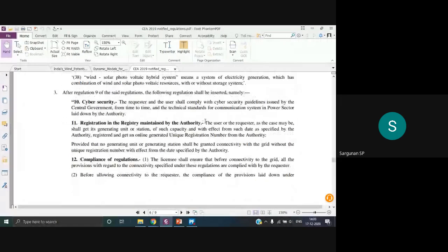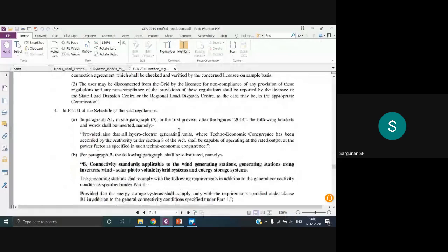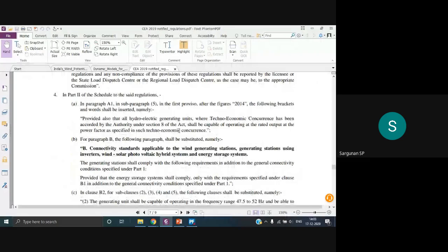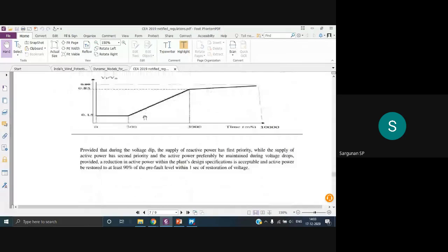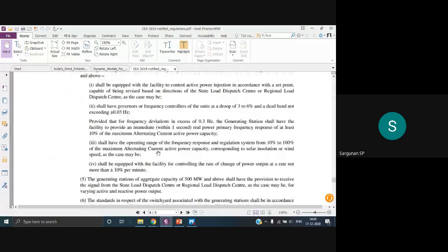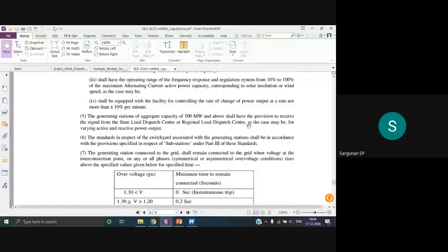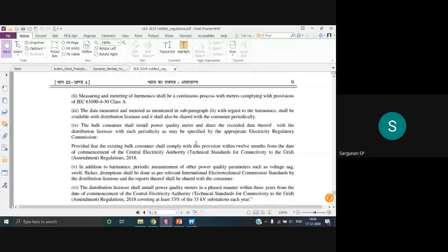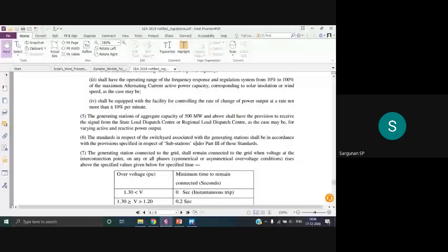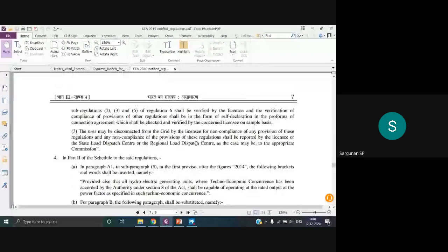What are all these studies? That is nothing but grid compliance studies. So first you will be doing the ride through studies. We will be calling this the fault ride through studies, whether it is low voltage or high voltage ride through. We have to mandatorily do these ride through studies, and the other thing is we have to examine the harmonics. What are the harmonics in the system? And similarly, we will also be doing the flicker, etc. I will explain what these fault ride through studies are.